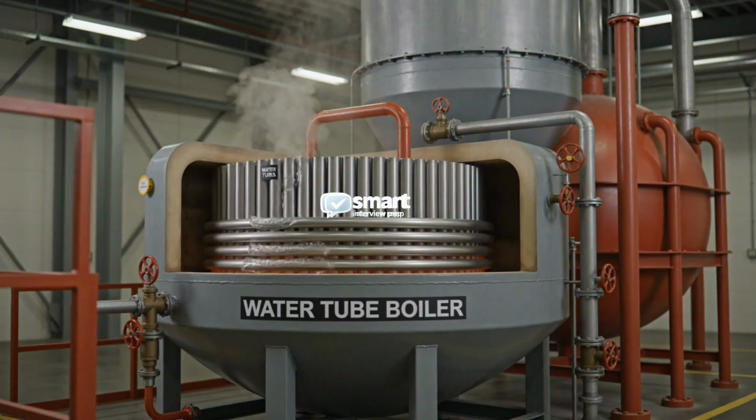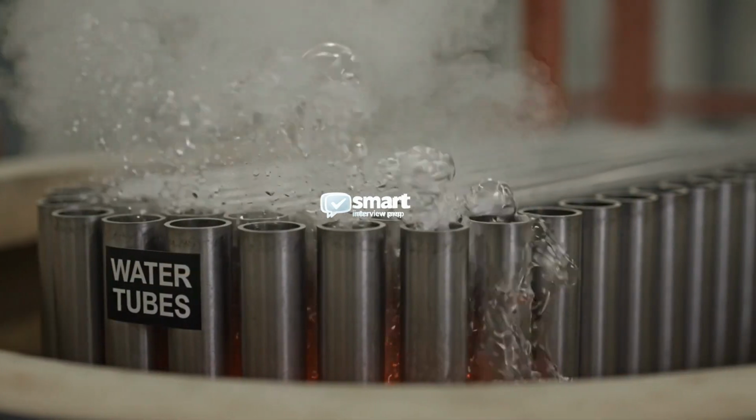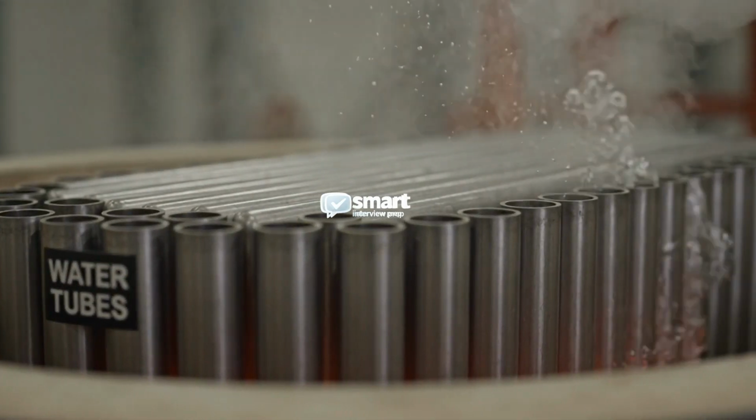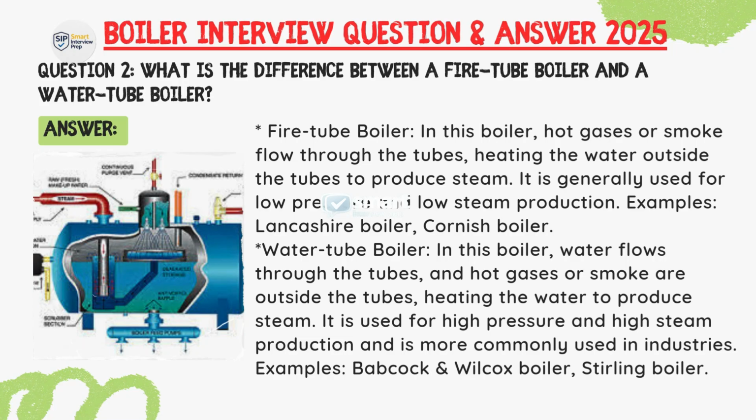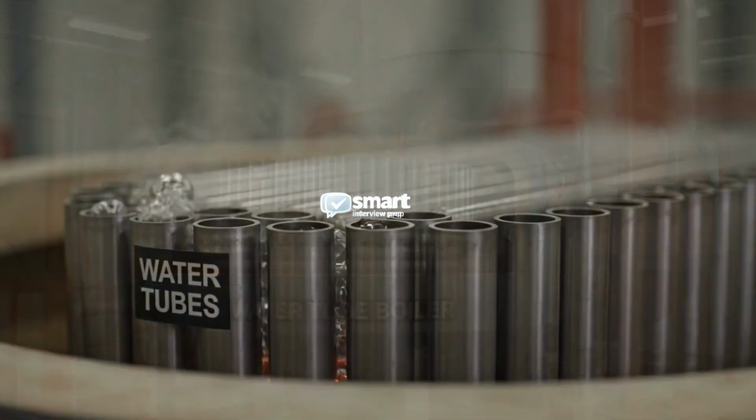On the other hand, water tube boiler: water flows through the tube and hot gases or smoke are outside the tube, heating the water to produce steam. It is used for high pressure and high steam production and is more commonly used in industry. Example: Babcock and Wilcox boiler.